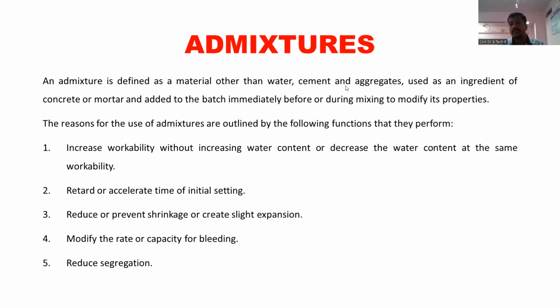It depends on the conditions in which you are going to cast your concrete. Whether you are going to cast in cold weather or hot weather, depending upon that you are going to decide. Or maybe the temperature effect also you will consider. Maybe the temperature is around 40 degrees or 40 plus. At that time, you use retarders to slow down the rate of heat of hydration. And if you construct in colder regions, there you use accelerators which will enhance the rate of heat of hydration.